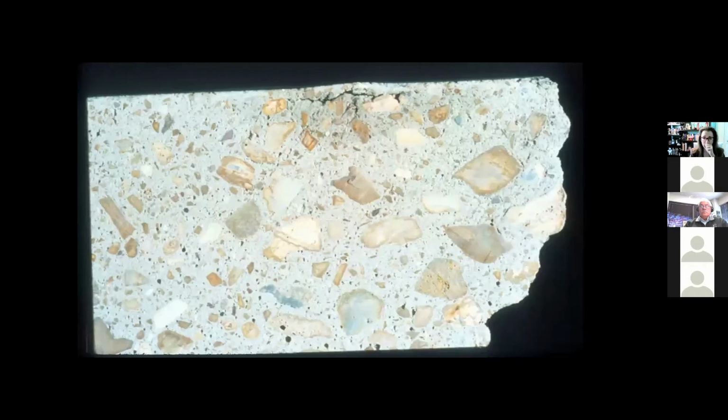So it could be the type of finishing too. You can seal the surface by using the wrong product, such as a steel trowel on air entrained concrete. That's something that does happen. What you see here is a close-up section of concrete where you can see the blister in the middle of the screen. It can also happen from just a high bleed rate, where bleed water gets trapped under reinforcing steel as well, but also at the surface. If it happens on formed concrete, formwork concrete, those will tend to turn into bug holes, and we'll talk about those in a couple slides.